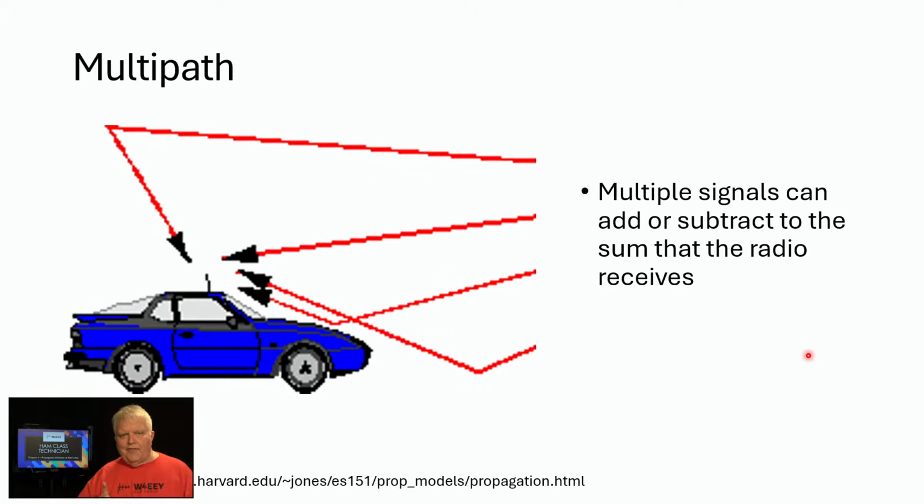That's multipath. You're experiencing more than one signal reception path coming to your car antenna in this case, and instead of being additive, it's being subtractive and taking away the signal, and that's why it went away. But if you move just slightly, you change the equation, you change the signal strengths, and you get your signal back. So if you've ever wondered why that happens, that's it.